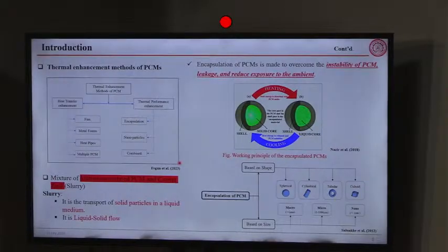So you can see how many research avenues we can think of when we are speaking about the challenges associated with thermal storage systems. There are certain techniques through which we can do it. Sometimes we call it micro encapsulation, where we encapsulate the actual wax in a sheath which is more hydrophilic, and that way the wax retains its heat storage capacity.